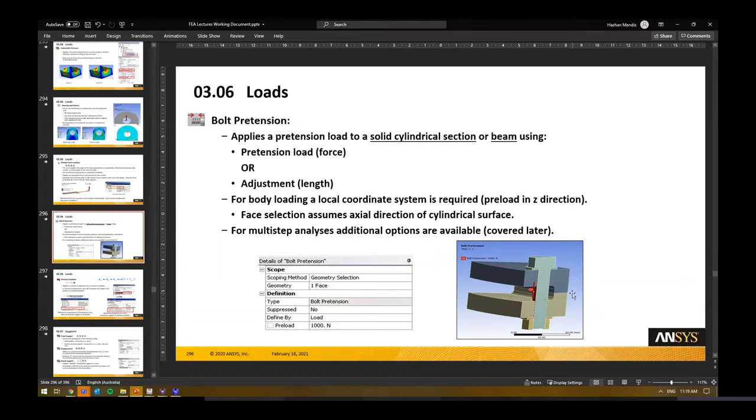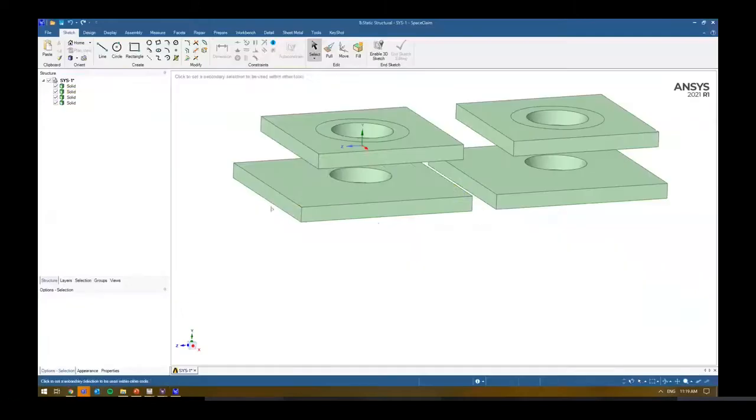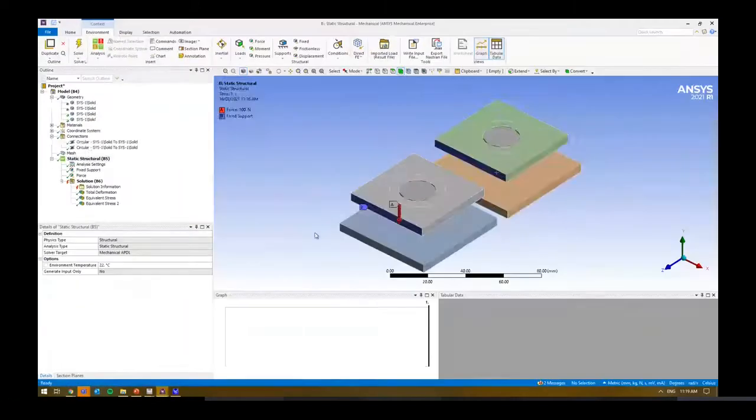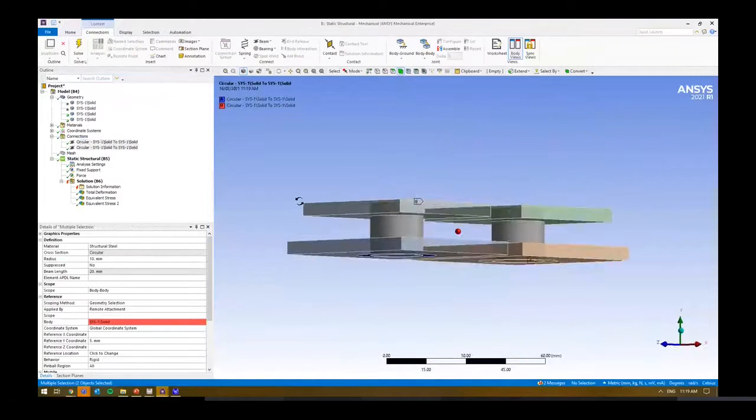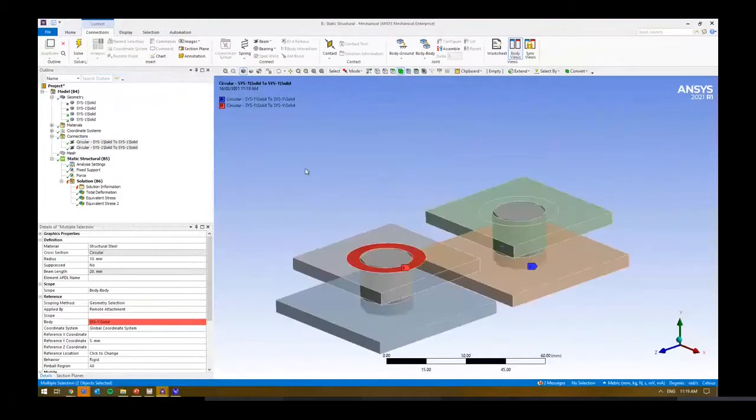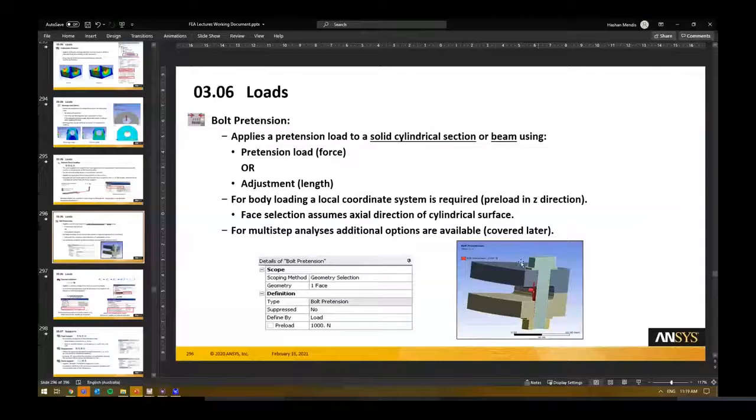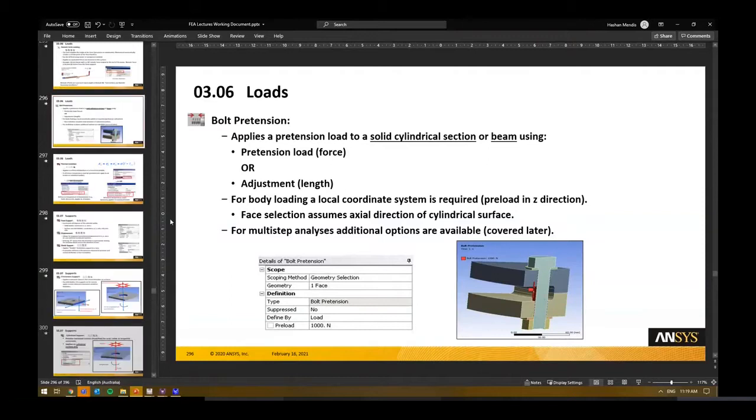On the right, we've actually CAD'd a bolt. We can see the 3D complex stresses going through the bolt shank, the head, as well as the washers, and the nut at the bottom. Similar to what we had here before, we can just model it as if it was a beam, connecting the top and the bottom. We're not going to get any complex forces or stress distributions or singularities because of the geometry at the top, but those are the types of simplifications that we make as well.